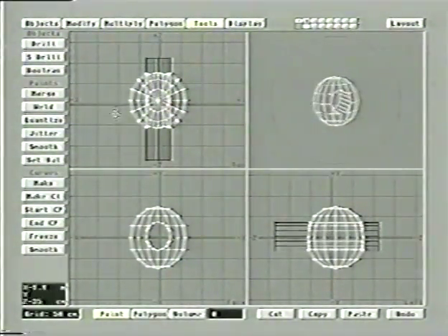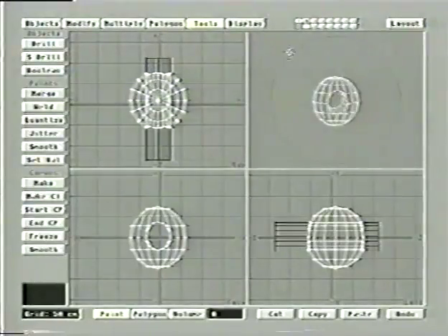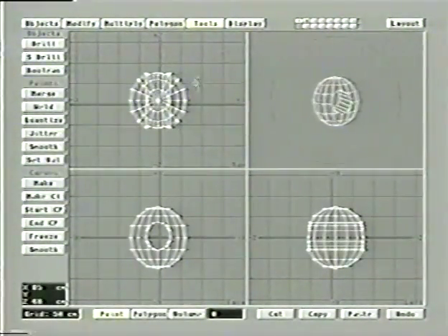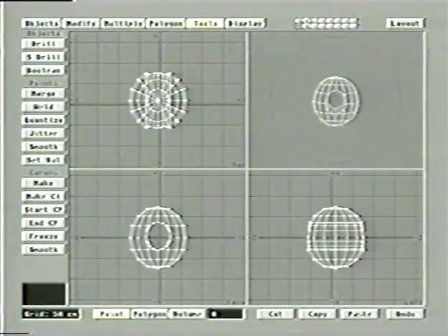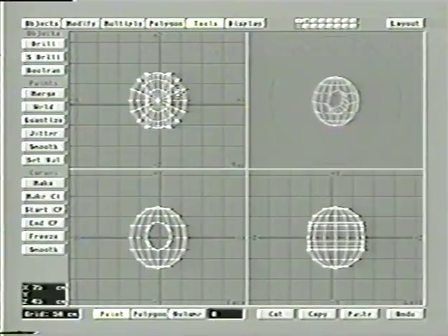Now, you'll notice that we can still see the disk, though. This sometimes throws people. We can still see the disk, of course, because it's on an inactive layer that's still selected. If we get rid of the inactive layer just by reselecting our active layer, let me click on layer 1 again. You see the disk isn't really there. It just doesn't get rid of it. It's still on layer 2, unaltered. But we can still see it in black because it does not automatically turn off the inactive layer when you do a Boolean. So here's a subtract, fairly simple operation.